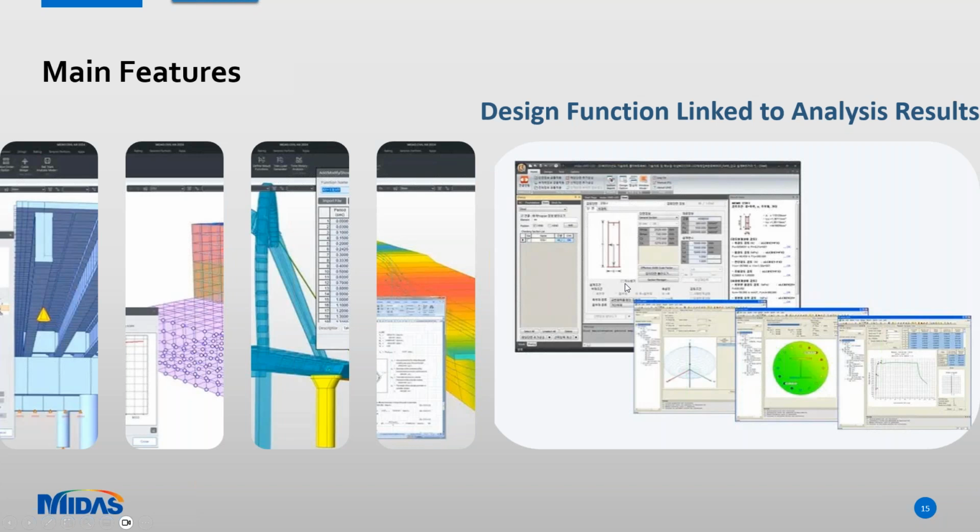One of the examples is to check the substructure or the foundation, let's say piers and piles, for which I need to check the stress check, interaction ratio, maybe the moment curvature relationship. For that, we can use the MIDAS general section designer tool.